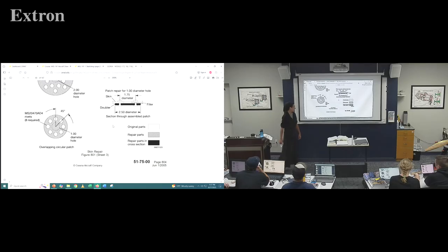Super cool thing, especially when you need a template to put onto sheet metal. Make a circle with your compass, cut it out. This one's big so that you can see it rather than just a 2.5 inch thing there. But if you fold it once, and then fold it again, and then fold it a total of 3 times, crease it really well, and then open it up, you're going to have 1, 2, 3, 4, 5, 6, 7, 8 lines, perfect 45-degree angles.